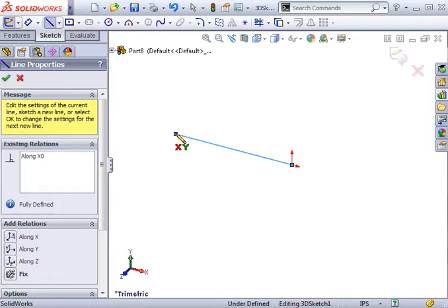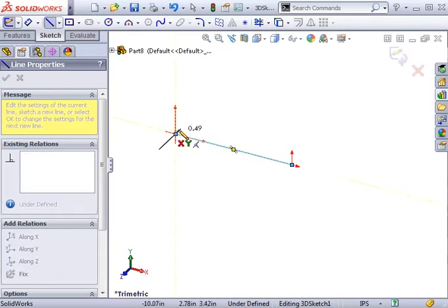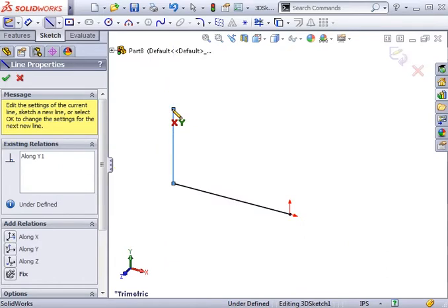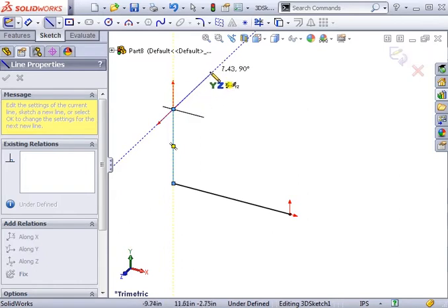When the segment is completed, you can see it in Properties in the Property Manager. Next, I'll sketch a segment in the Y direction about 8 inches long. The next segment will be in the Z direction, so I'll press the Tab key to make the YZ orientation active. You'll see the YZ feedback next to your pointer, and if you pass it, keep pressing Tab until it reappears. The segment will be approximately 6 inches in the Z direction.